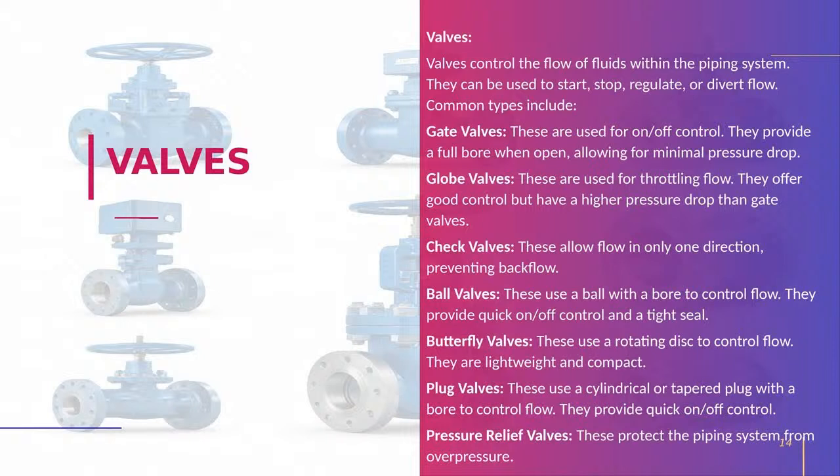Globe valves are majorly used for throttling the flow. Majorly we will be using them in the bypass. If a control valve, which is a flow control valve, is there, there will be a bypass arrangement. In this bypass arrangement, 99% we will be using the globe valve. Why? Because of its construction. The gate valve's internal trim will be different, and in the globe valve it will be different. That's why globe valves are majorly used in the throttling or controlling process.